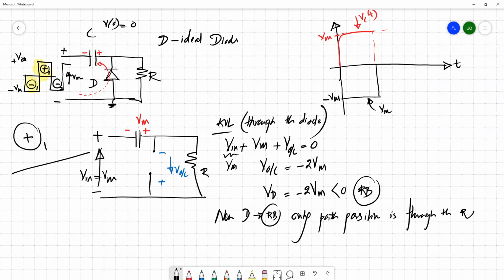Now this diode gets reversed, so you will end up with a circuit containing this capacitor and a resistor. Based on the previous assumption made, the RC constant, or the time constant, is pretty large for this particular RC circuit.